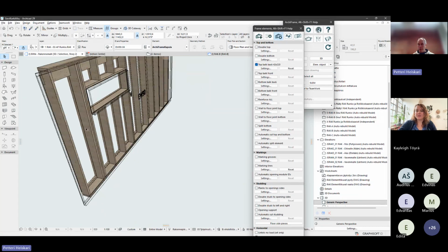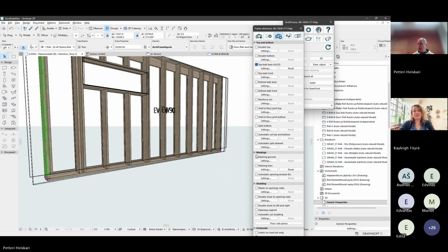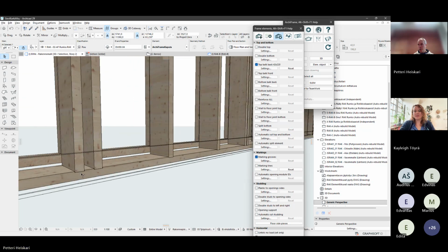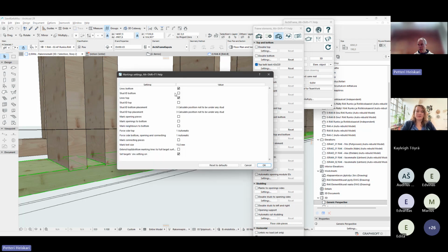And then if you have a cut saw but not a framing station, then having marking grooves will help you assemble this element. So the marking grooves show the position of each stud like this. Then another option, I'll set the settings for marking lines to be on the front side, on this narrow side, because that works the best, at least with Hundegger CNC.